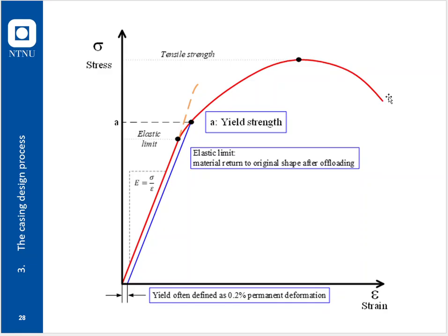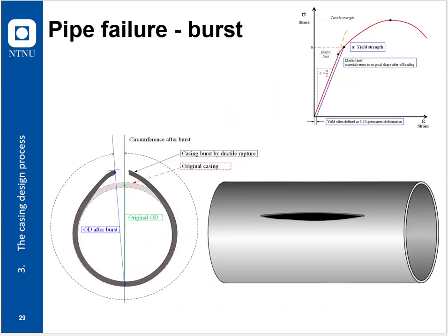There is a specific calculation in ISO 10400, the API 5C3, where you calculate rupture of pipe. That's very easy, because that's where you see pipe failing, and it ties into all the good calculations. It's the specific yield, and then you know the wall thickness, or the parameters of the pipe, and you can calculate rupture quite easily, and you can see it. Science is tied to what you can see, measure, and